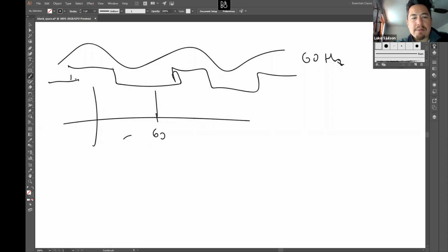Then what you actually get is harmonics, at 120 hertz and 240 and so forth, at multiples of 60. You also get this content. So this is often called a spectral line, meaning it's a line in the power spectrum. The power spectrum is the real valued function. It's basically the Fourier transform squared. So it tells you how much of each frequency is present, but it doesn't tell you the phase information. The phase information is stored in essentially the complex part of it.